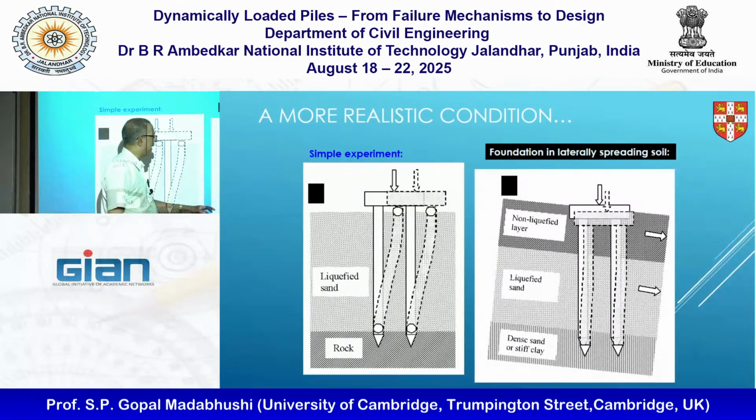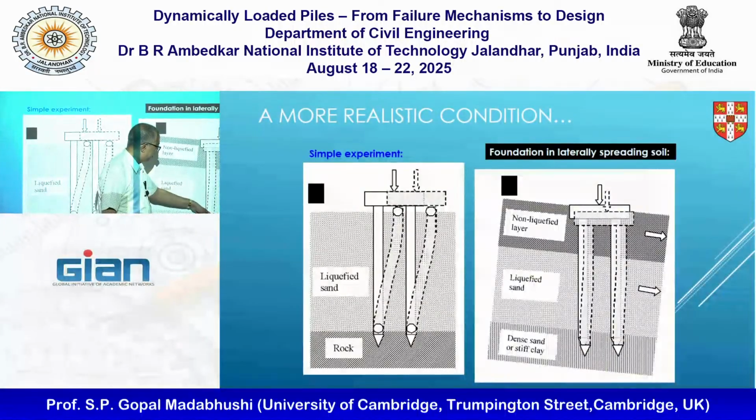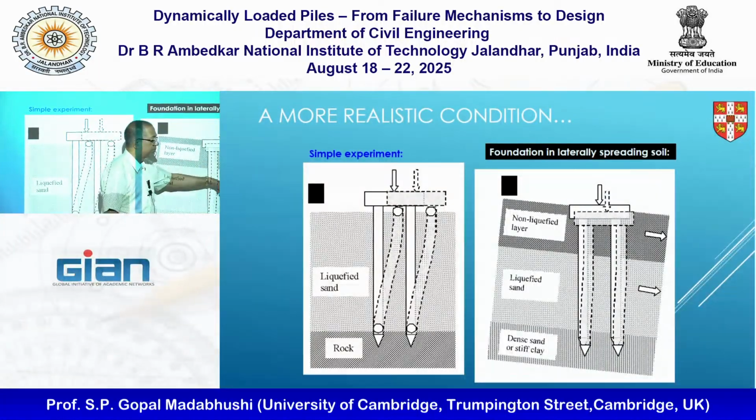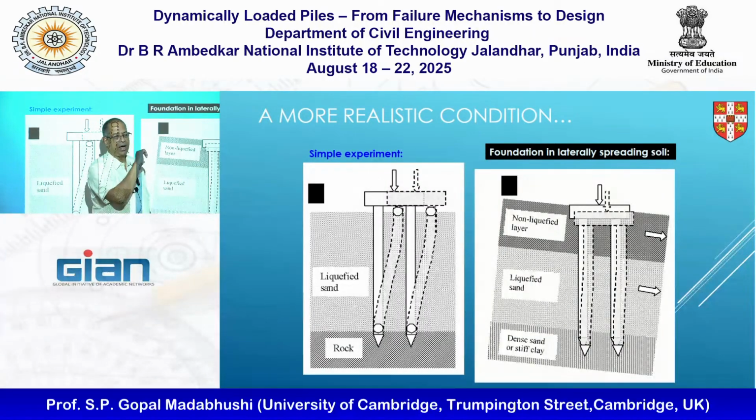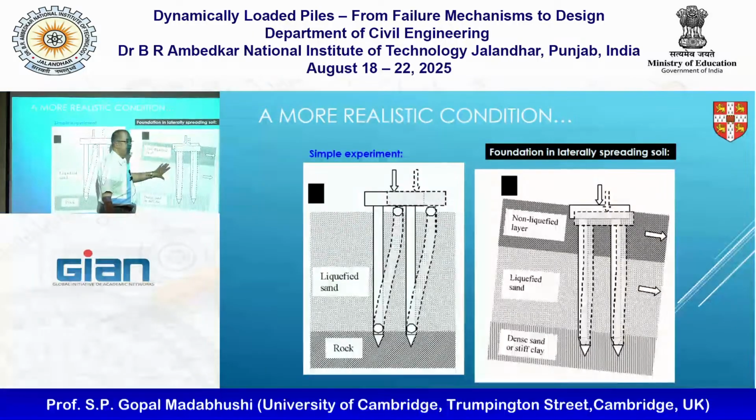That doesn't mean the pile won't have bending. The pile will still, it's settled, but also it is trying to bend a bit. So you're still in the bending regime I've shown you in the morning. Okay, so you get some settlement and some lateral movement and also some bending, because this obviously doesn't move laterally as much as this can. This one is going for a ride with this layer. This is sitting on the liquefiable layer.